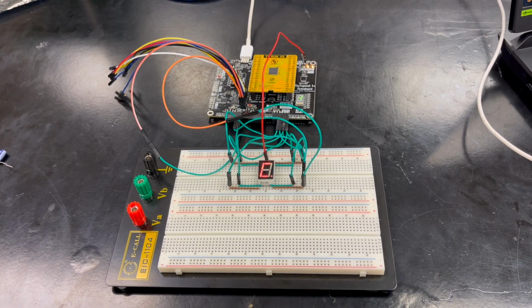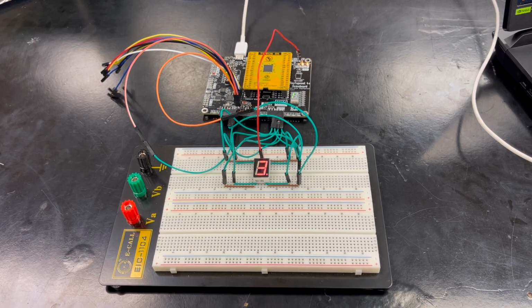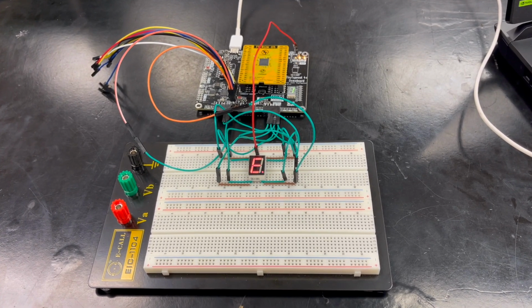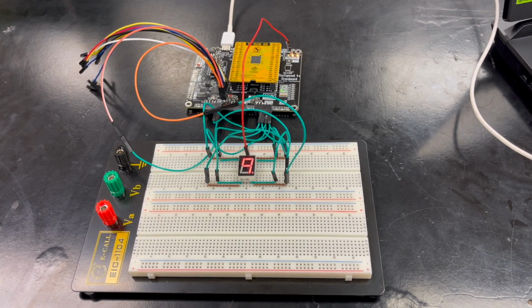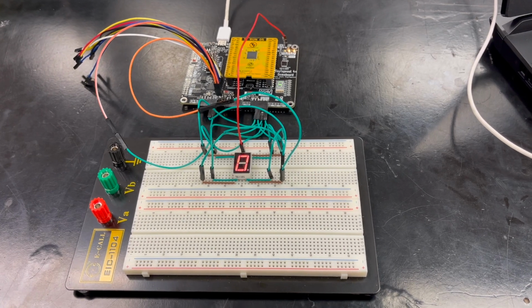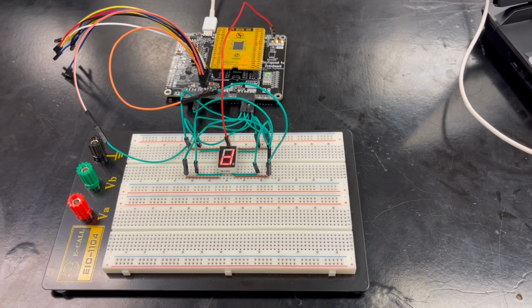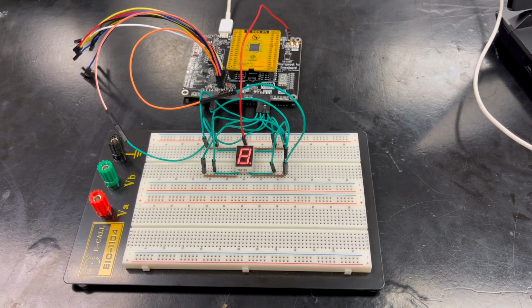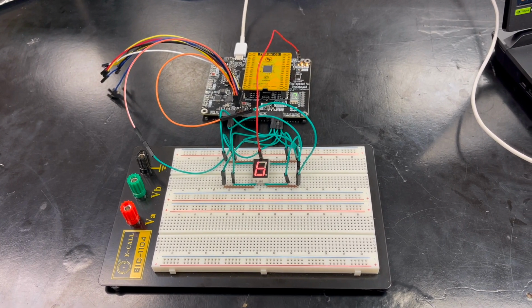Welcome to our presentation and demo on the PRBS pseudo-random binary sequence generator. This chipset currently generates 15 sets of numbers or letters in hexadecimal form, which are displayed on a 7-segment display for each cycle. While these sequences appear random and serve as a solid proof of concept for testing data, it's important to note that they aren't suitable for encryption, as the cycle sequences aren't long enough to ensure security.